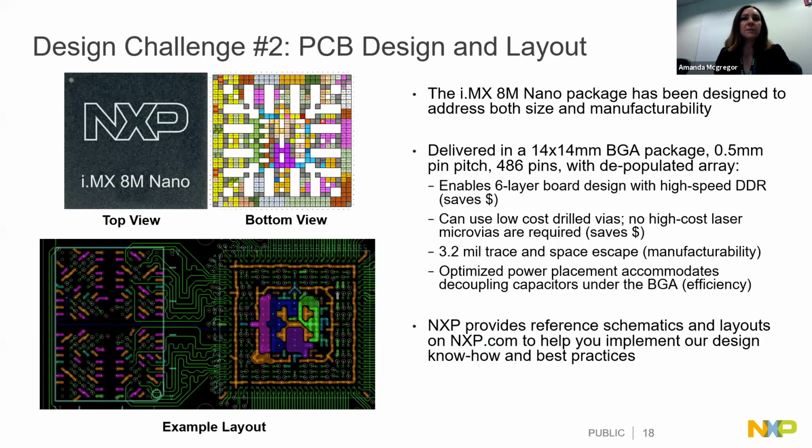So we're trying to create a really balanced approach of physically making the parts small, because that translates to being able to support space-constrained devices, but also saving you PCB cost as well. The smaller the XY area on a PCB, the less you pay. So there are efficiencies in cost to be realized from a small package as well. But we don't want to go and make it a 0.4 millimeter pitch. So we decided 0.5 millimeter is the pitch we need.